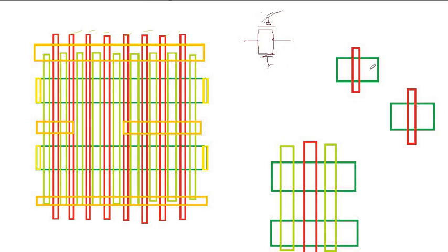I cannot place these two transistors one below the other. Just assume that this is a PMOS, this is an NMOS. I cannot place them next to each other with a small gap. Why? Because my gates would get short. So in a planar device, I would end up placing them slightly apart with one poly pitch difference. I would have to make the connection like this and then pull out the gate connections from here or from here, depending on whatever is feasible over there.